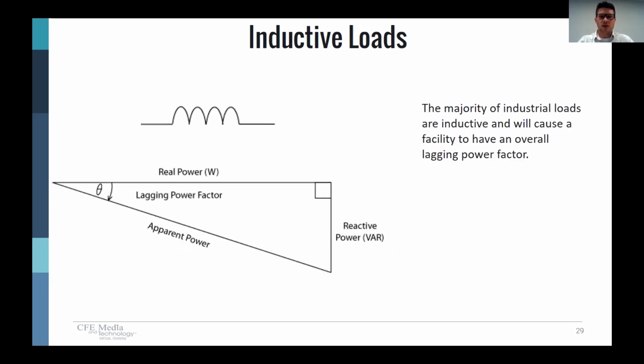Typically, the electric loads that we are dealing with in our industry are inductive loads, like a motor, for example. That simply means that the load current lags behind the supply voltage. And FYI, lightning bolts, believe it or not, are actually inductive loads. The majority of industrial loads are going to be inductive. So our power triangle is going to look like this, and we're going to be dipping below the x-axis. So now, finally, to the point, how can we minimize that reactive power?